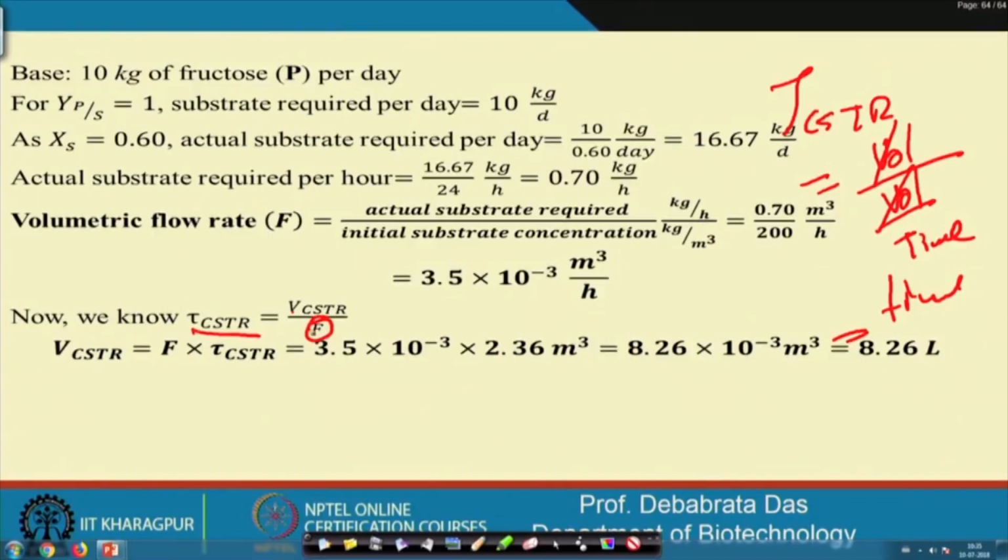Now here, how much product you want to produce? 10 kg of product. For 10 kg of product, how much substrate is required? 10 kg. Now what is the percentage of substrate conversion? It is 60%. The 10 divided by 0.6 is the actual amount of substrate that is required. So then you can convert it. If this is per day, you divide by 24, then you will get 0.7 kg of substrate you require per hour.